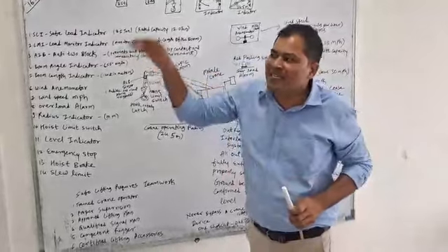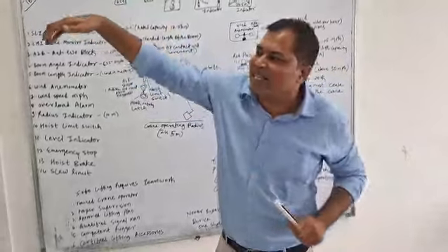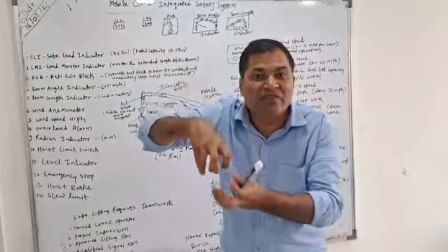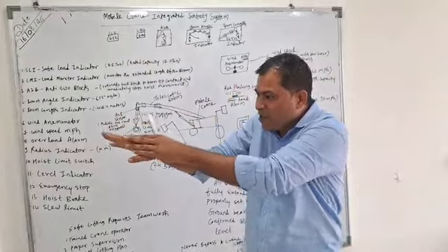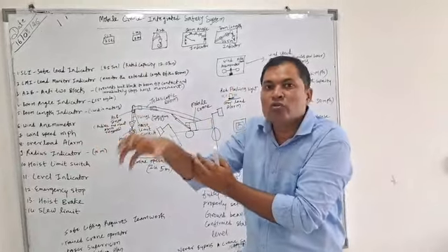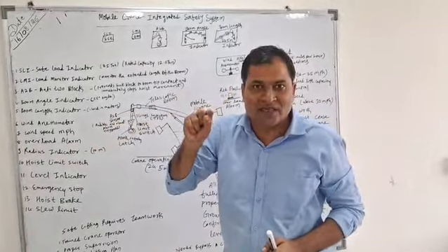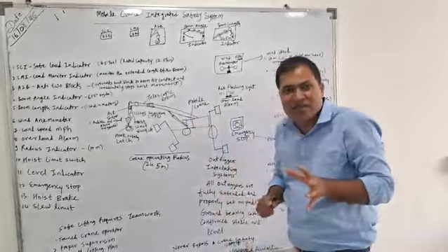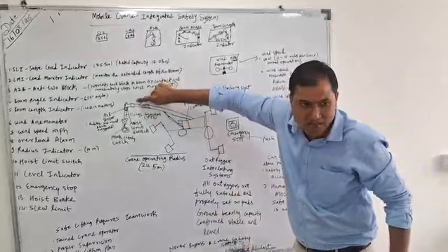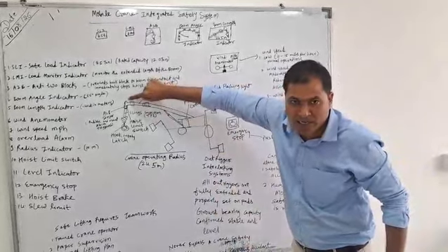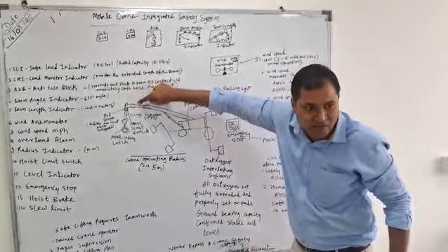So once you start extending a bigger area, your lifting capacity goes down. Understood? If your extended boom goes back, your lifting capacity also increases. Why is it very important? Because once you extend the boom length, it is totally open, so you have to go back for the safe limit as well.